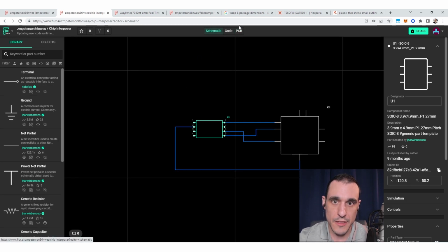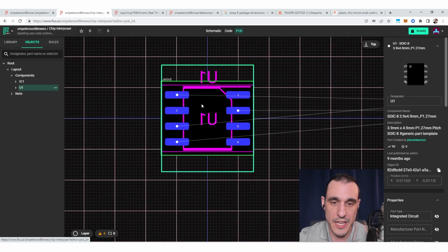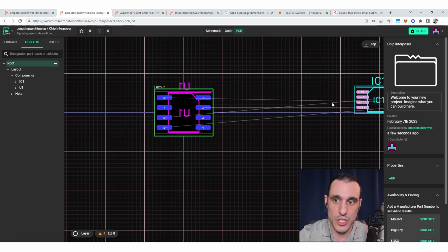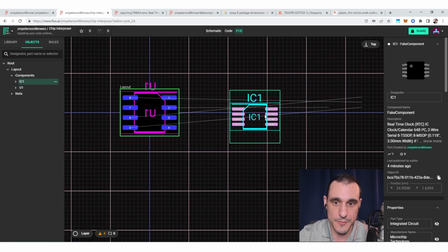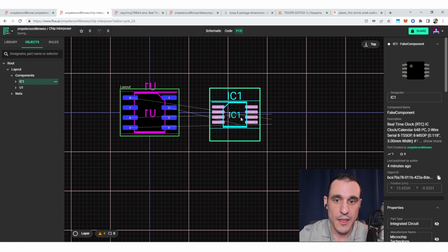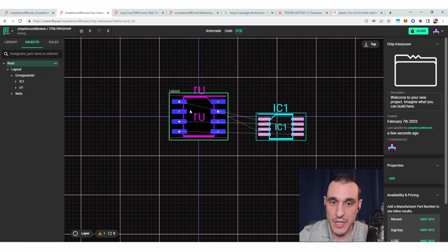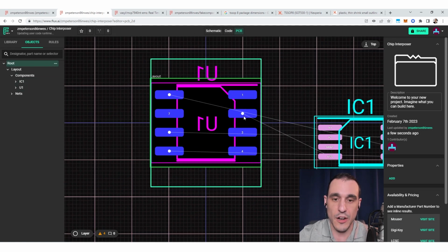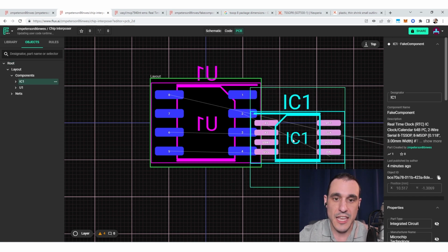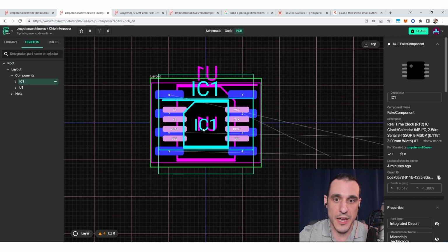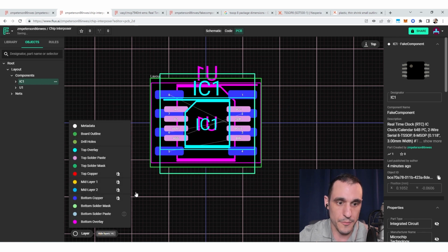Now notice here that when I took U1 and put it on the back layer, it actually takes that component and flips the pad orientation. So because that pad orientation is flipped around, you need to check the pinout on this pad compared to the connection that you need to make on this pad for these components. Now, once I've got that pinout verified and I have these connections verified onto these pads, I can take my IC that I want to use in my assembly, and I can just drag it over here.